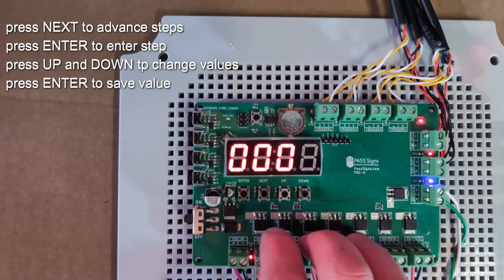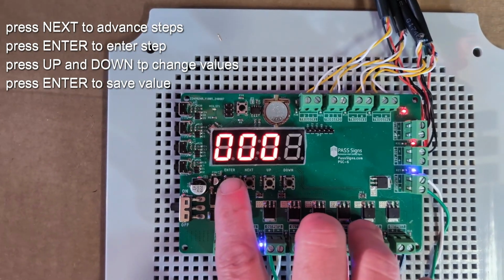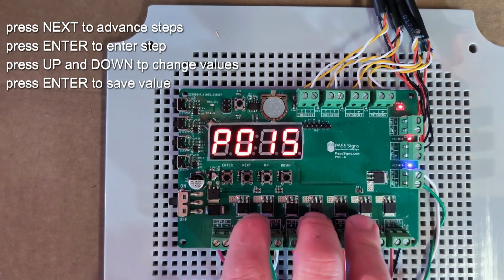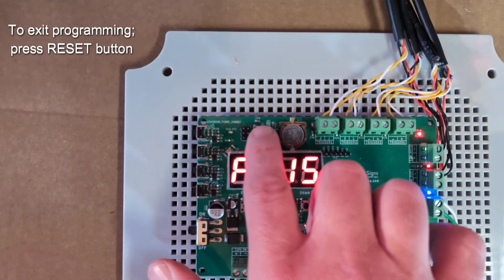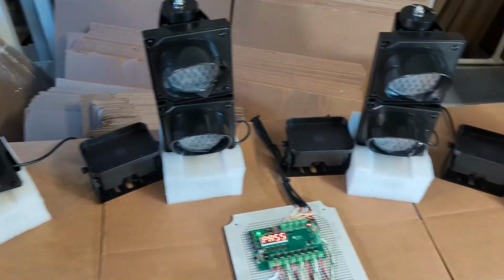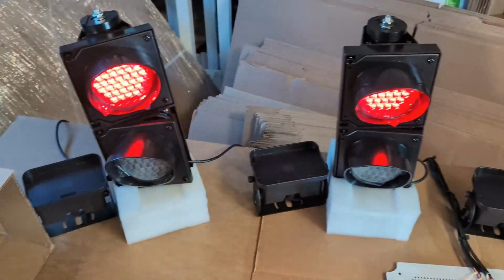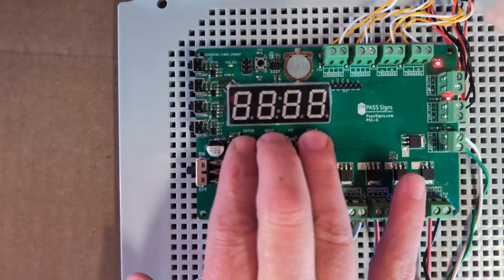I'm going to hit enter. And I'm going to change this to 0, which makes it all reds mode. Hit enter. And then to escape or exit programming, I'm just going to push the reset button. And now our lights are going to go from all greens to all reds. Okay, ready to go.